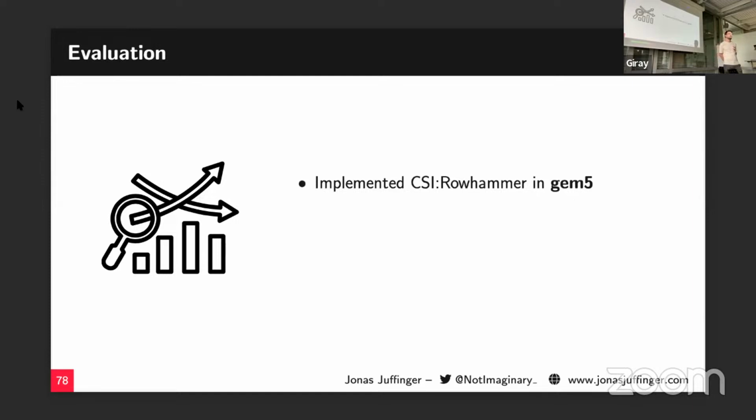Not really, actually. One reviewer, we also have this in the paper, noted that it's quite common that a single connector on a DIMM is broken, so that if you read data, it's always the same location that's wrong, or always reads a 0, or always reads a 1. We evaluated in the paper how we could correct this and how long it takes. But we made really clear in the threat model that a full chip failing is not what you care about, because ECC also cannot do it. And chip kill can. Chip kill, yes. But your normal ECC cannot do it.